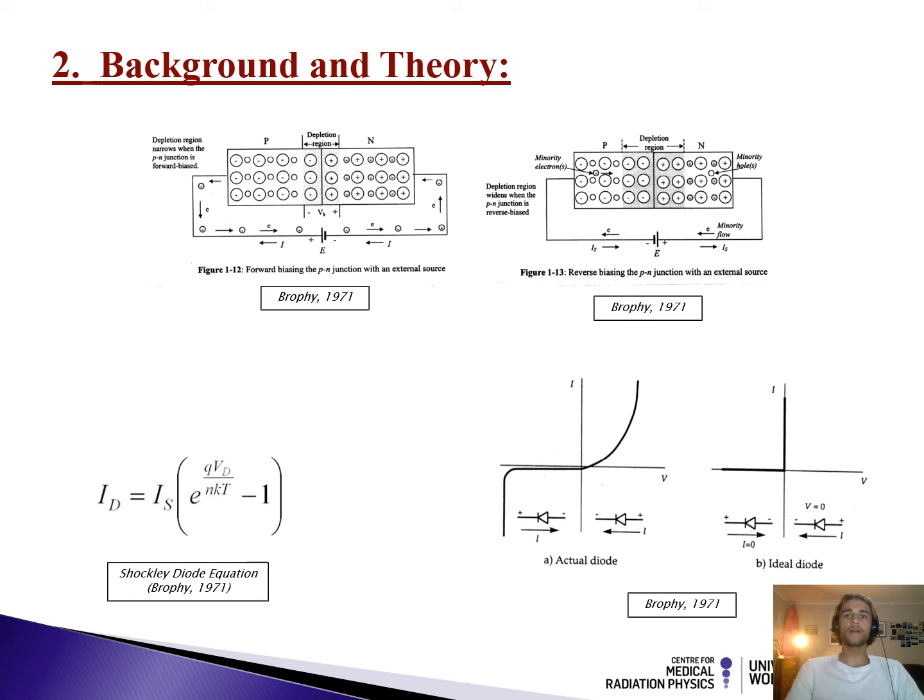This results in a wider depletion region than a standard diode, increasing the breakdown voltage of the device. Another type of diode is a Zener diode, which is designed to have a precise breakdown voltage that can assist in voltage regulation. Unlike most diodes, the Zener diodes allow current to flow backwards when a specified reverse voltage is reached. This is known as the Zener voltage.